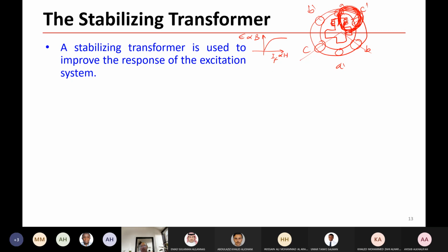So if you increase the field current here, it increases linearly, but when you reach a level of flux, we have now saturation, and this of course will affect the reluctance of the magnetic path and inductance and so on.